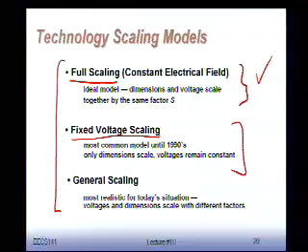But you can imagine that if I put more and more transistors and I keep my supply voltage constant, my power is going to go up through the roof. Because I'm switching more and more devices faster and faster and faster, so power killed this guy off. So people started scaling the supply voltages as well. 5 volt, 3.3 volt. And then for a while it was actually quite simple. You look at your technology node and you know what the supply voltage is. If it's 180 nanometers, 1.8 volt. 130 nanometers, 1.3 volts. 90 nanometers should be 0.9 volt.